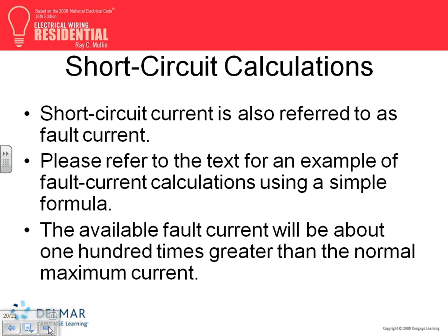In the older buildings with older wiring, do you think fuses are better than breakers? For knob and tube? Not with the tampering. Ask people how many have put pennies underneath them, and they're oversized.